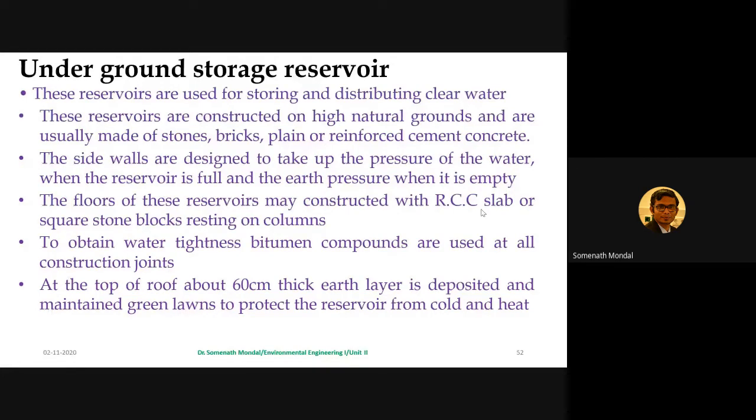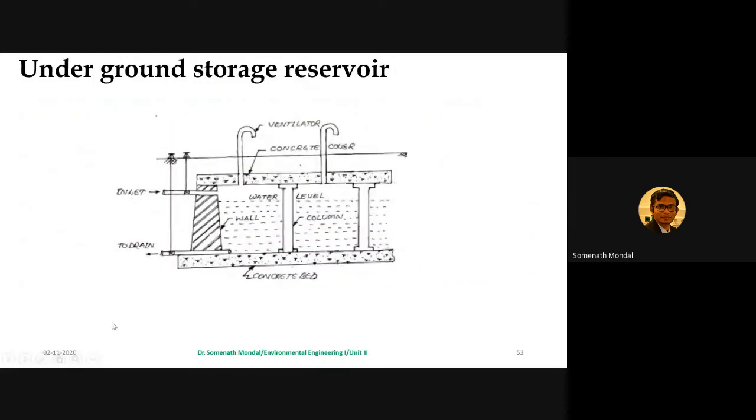Now the side walls are designed to take up the pressure of the water when the reservoir is full, and you need to think of this particular point very well, that when it is empty, the earth pressure will apply pressure in the other direction once it is full. So let us try to understand this fact from this particular figure.